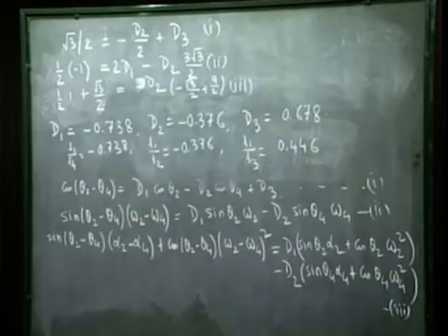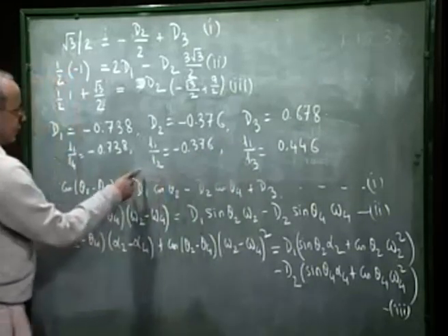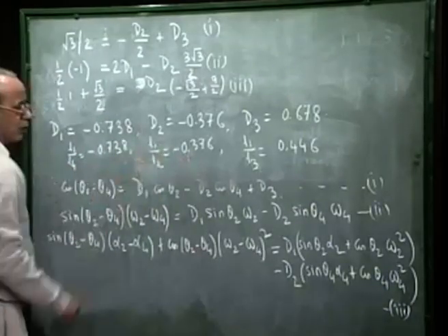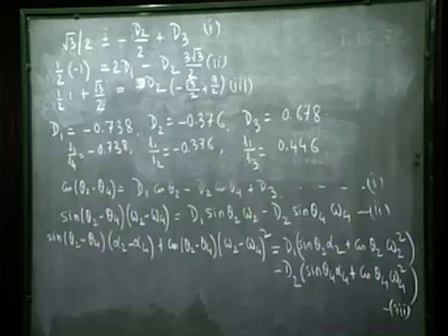So, we get all the three link length ratios, and as we said, L1, L3 are always positive. For this particular problem, L2 and L4 are turning out to be negative. So, if we choose the length L1, we can solve for L2, L4 and L3.